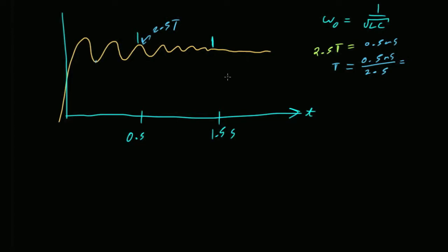Do we need to do a lot of exponentials to figure out the time constant? 3 what? Time constant is 3 milliseconds? No. 63% of the total of the highest voltage. You could do it that way. But if I just want to get a quick and dirty, divide by 5. It has to settle completely within 5 time constants. So you could say 5 time constants is 2.5 milliseconds or 3 milliseconds. I could take any of those, okay?